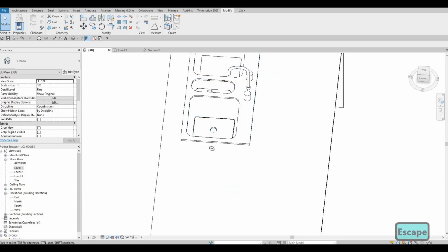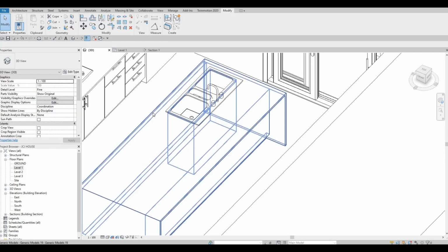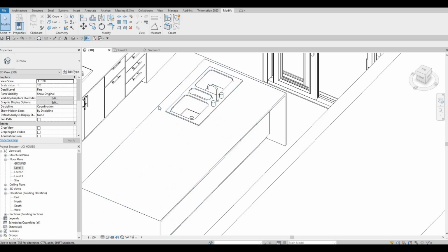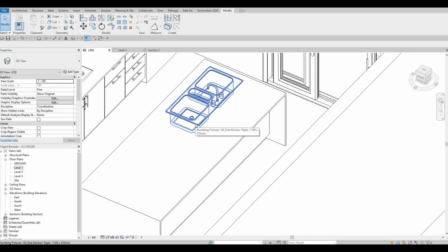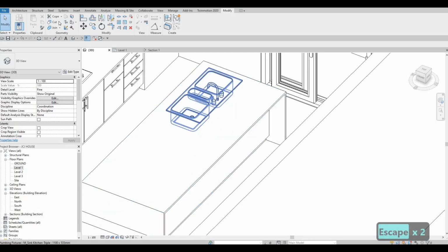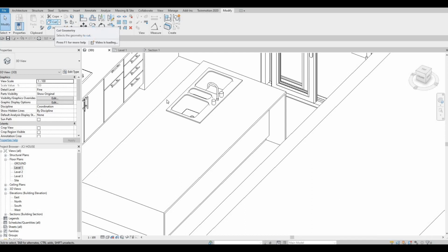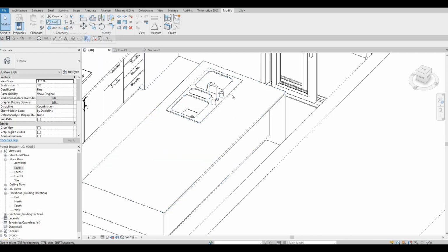Now it's showing the bottom because you need to select which are multiple cuts. You want to cut it here and then you want to cut it here as well. So those are multiple cuts. That's why when I was clicking cut geometry, I was selecting this one as well, and then cutting, and then selecting this one, and then selecting the void extrusion.